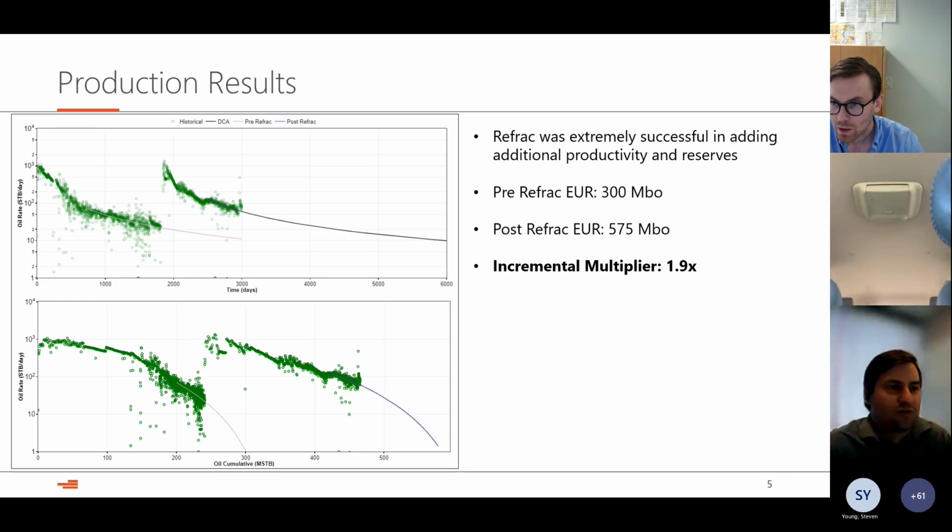It certainly does draw down typically a little bit quicker, but we do use a pretty similar choke strategy. So probably the total drawdown is a little bit faster on a post refract than the original well, just because of typically having more contacted new virgin rock than the original life of the well. But the strategy from a choke management standpoint looks relatively similar.